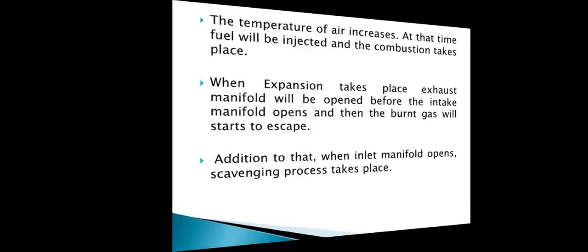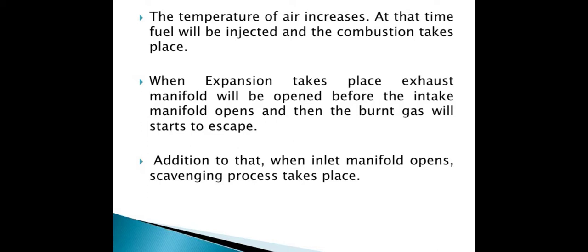The temperature of the air increases. At that time fuel is injected and the combustion takes place. When expansion takes place, the exhaust manifold will open before the inlet manifold opens, then the burnt gas will start to escape. In addition to that, when the inlet manifold opens, the scavenging process takes place.